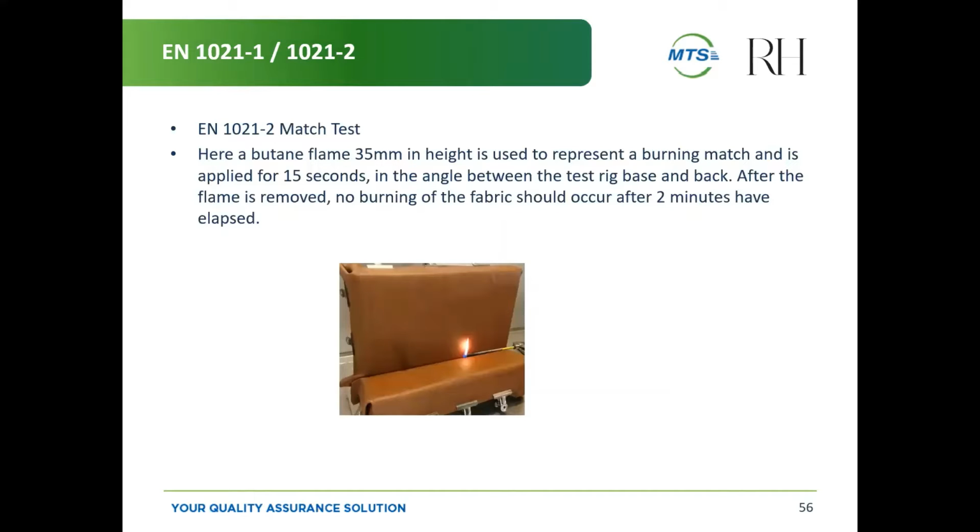Now EN 1021-2, this is the match test. Here again, we're using the butane flame. Most labs would be doing that. And it's applied for 15 seconds right at the nook or the angle between everything. And then after the flame is removed, there should be no burning of the fabric after 2 minutes.